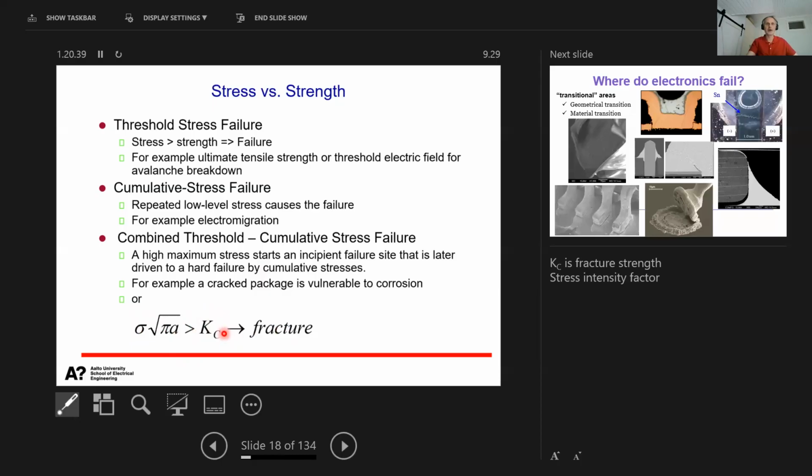Maybe one more example here. You have your glass window. You apply certain stress to your glass. It's not failing because glass is really strong, but glass also has quite low fracture toughness, meaning that if you have a minor scratch in the glass, then you need much smaller force to break it. Now this is used when we want to cut glass into smaller pieces. We use the diamond pen and then we bend it and then it cracks. Okay, let's go forward.